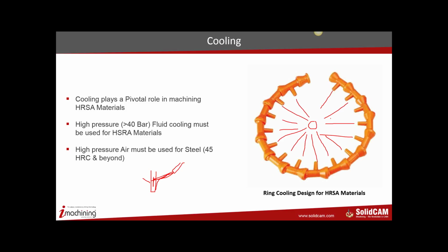So the cooling design is very important. Fluid cooling must be used for all superalloys. If you're cutting stainless steel, if you're cutting titanium, if you're cutting Inconel, it must be fluid cooling above 40 bar. For steels, it's different.